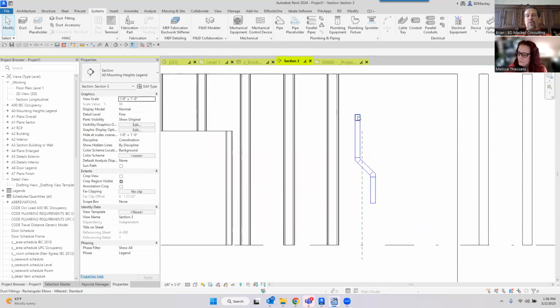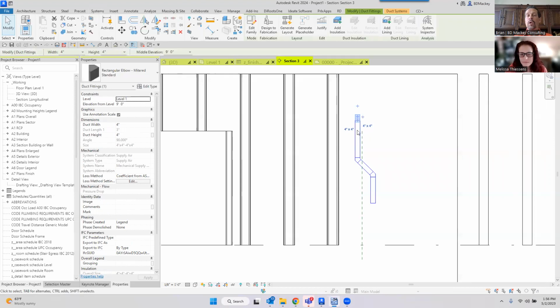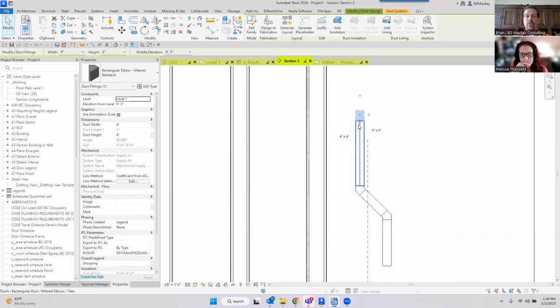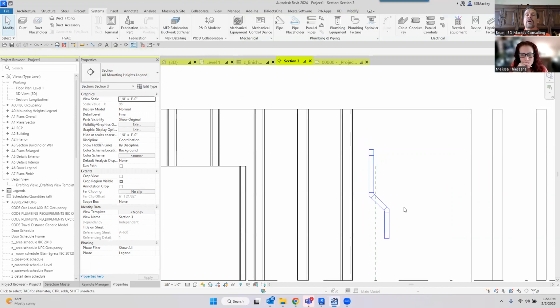Now I've done that. And like I said, rather than starting with a horizontal pipe, what I do is I have a collector, so I put that in, or if I'm going to tap into my downs or my gutters I've modeled on the roof, I have a face-based family that I can just place. Then I get the same scenario: right-click, draw duct, and now I've drawn my downspout. You could do it as round, you could do it as oval, whatever you were thinking, and now I've drawn those in. I've seen people create some very nice parametric crazy families, and I'm like, yeah, no, I just draw duct work.